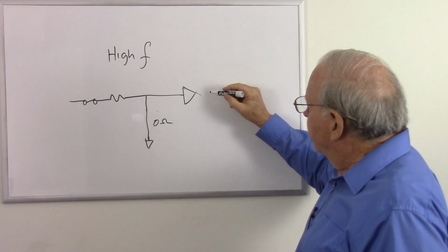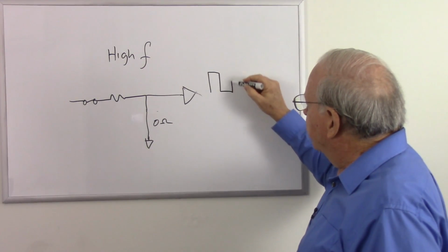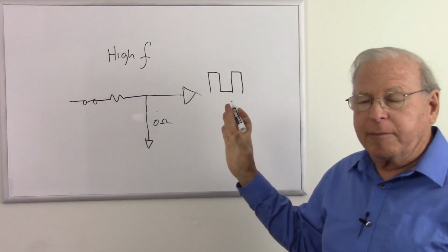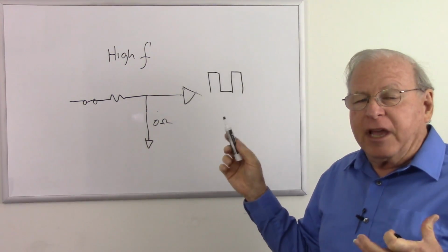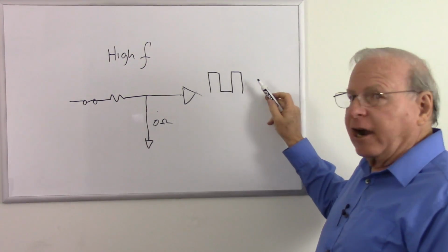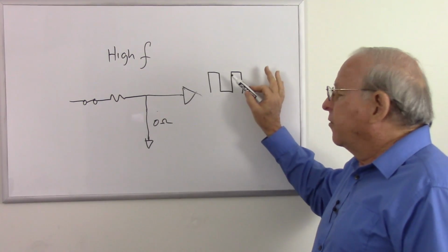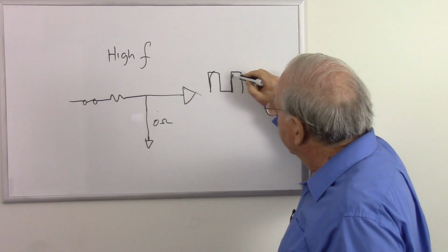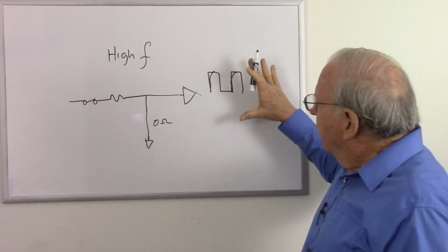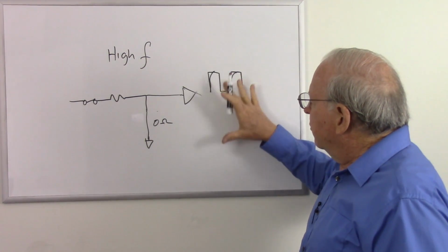Without this filter, this is going to tend to saturate and give us square waves. We basically have an astable multivibrator, and those square waves contain all of the odd harmonics, which are higher and higher frequencies. So if we can filter out those high frequencies, it's going to cause this to round off on the leading edge. So we want to eliminate those high frequencies.